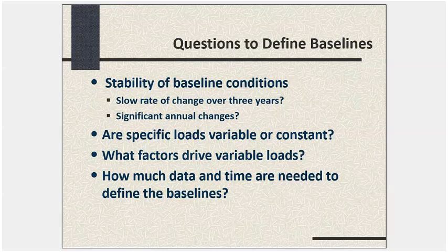Sometimes there's a phenomenon called load creep, or plug load, in buildings particularly, where people keep adding more and more electronic equipment and more load, and the load is gradually creeping up, not because the ESCO project didn't do what it was supposed to do. Maybe it did, but when you try to look at the utility bill, you're not accounting for load creep of plug loads that are being added to the system. And unless you're scrupulously monitoring it in terms of the internal complement of plug equipment, you might not realize what's happening.